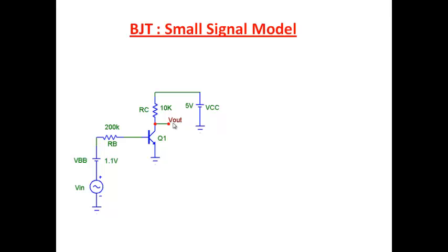So the way we find out amplification is, when we are talking about amplifiers, we are interested in knowing what is the effect of this input voltage here. That's a small incremental voltage that we have applied, and we want to know what is the impact at the output. So whenever we have an incremental voltage or a small signal voltage, we build a small signal circuit.